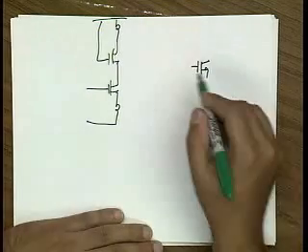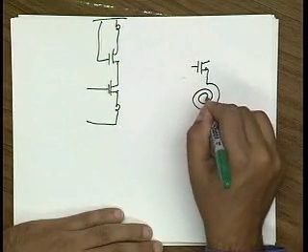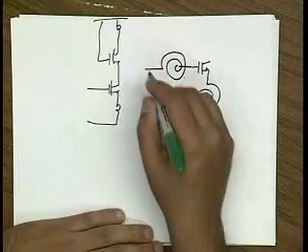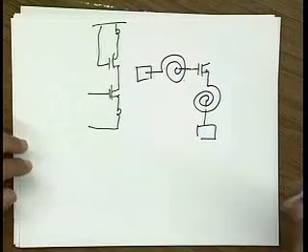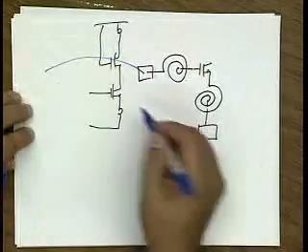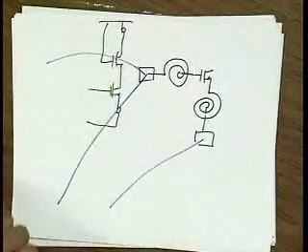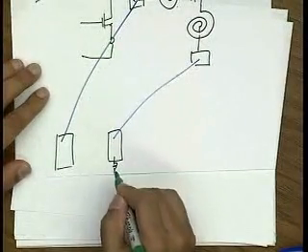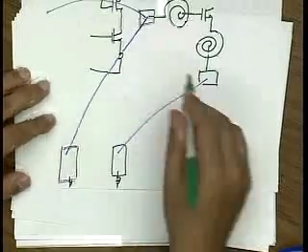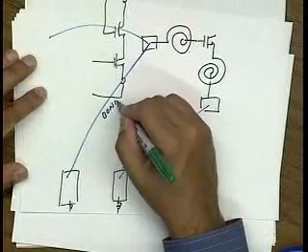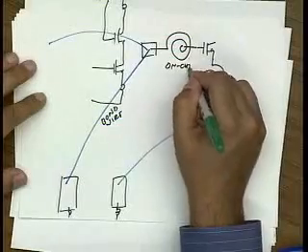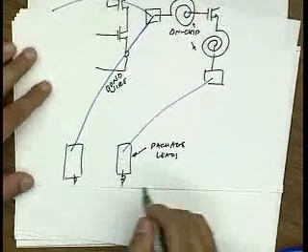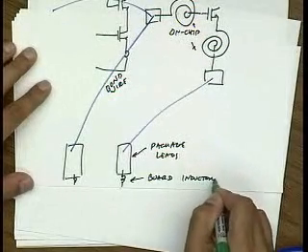So let's say this is my transistor. I can put part of LG on chip as a spiral inductor. Okay? LS and LG. And then this goes to a pad. Then I have my bond wires, and then I have my leads again. And I can actually then place a physical inductor here as well, if I want, and here. So the actual inductance has many parts. There's the bond wire portion. There's the on-chip portion. There's the package leads. And then there's maybe board inductors that we use.